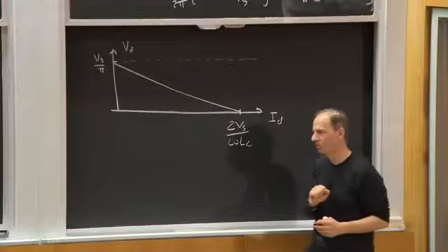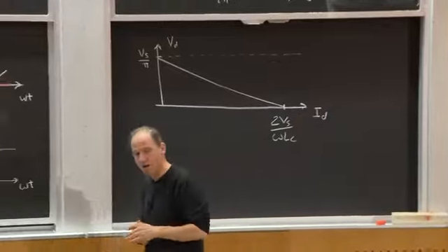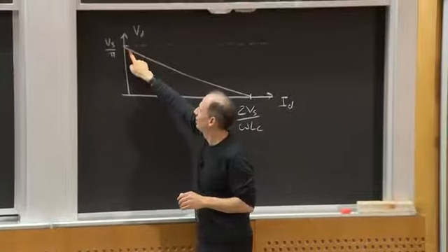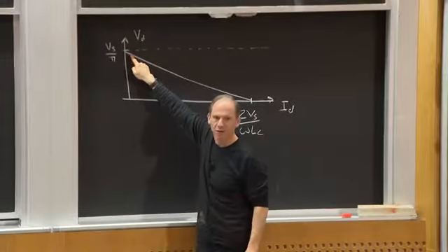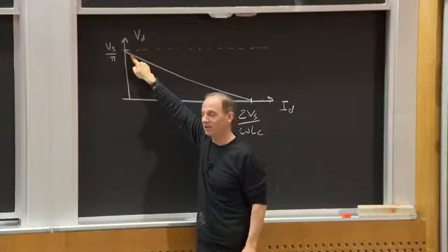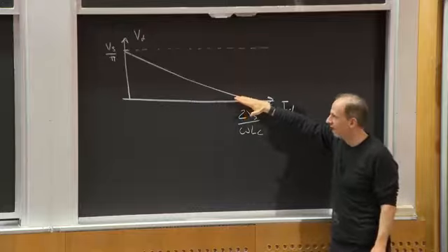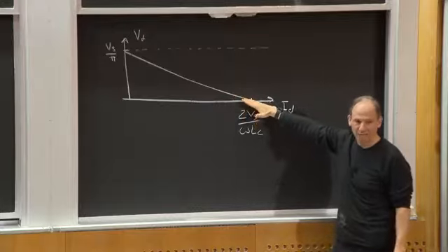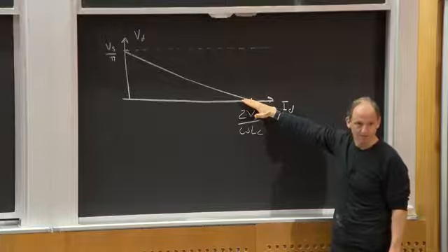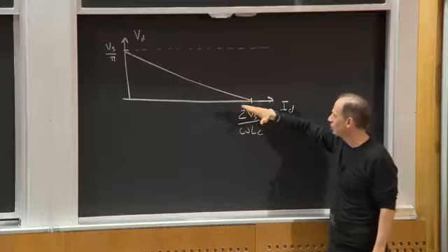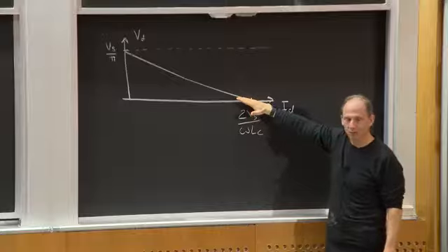Okay? Now, do I care? Well, if LC is really small, and for full current I only droop 1%, no, I don't care. If LC gets too big, however, maybe I have a problem. In fact, this actually limits the amount of power I can get out of that source. Because if you think about it, if I draw too much current, I get 0 voltage, so I'm not really getting any power at the output.